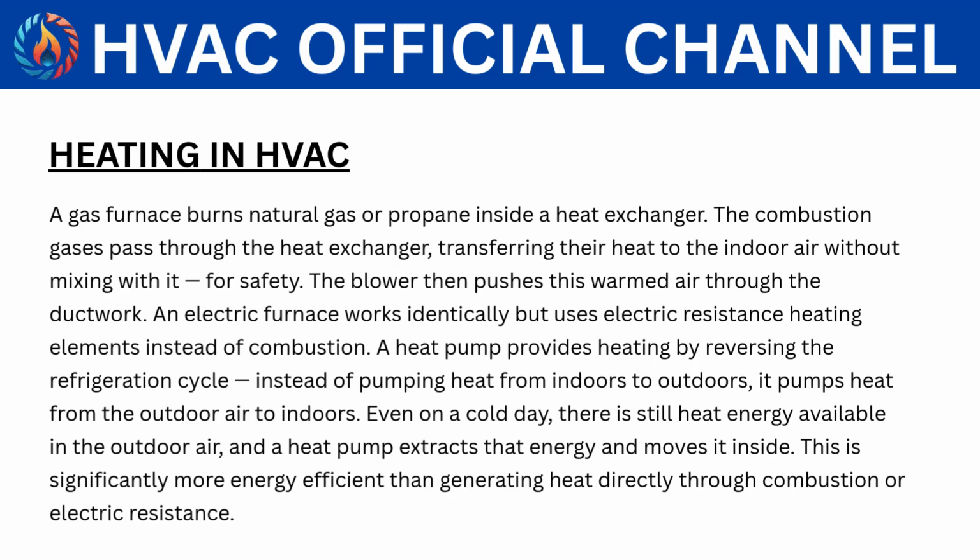A heat pump provides heating by reversing the refrigeration cycle. Instead of pumping heat from indoors to outdoors, it pumps heat from the outdoor air to indoors. Even on a cold day, there is still heat energy available in the outdoor air, and a heat pump extracts that energy and moves it inside. This is significantly more energy efficient than generating heat directly through combustion or electric resistance.